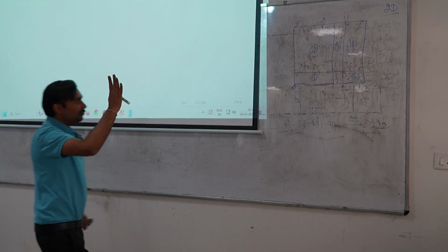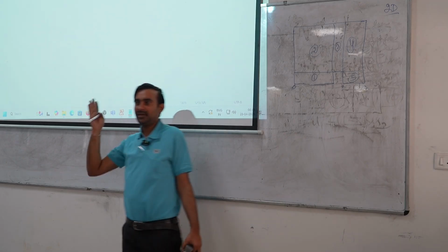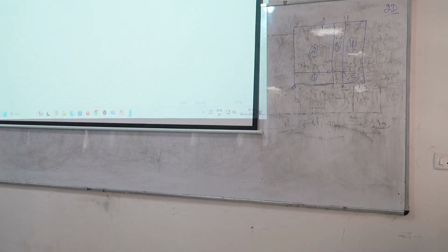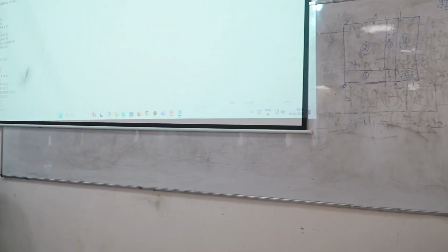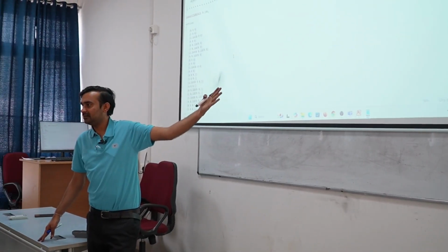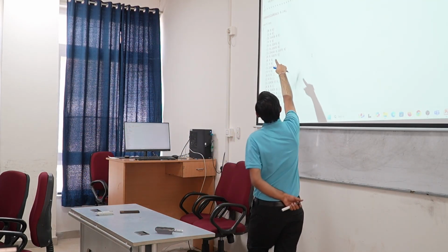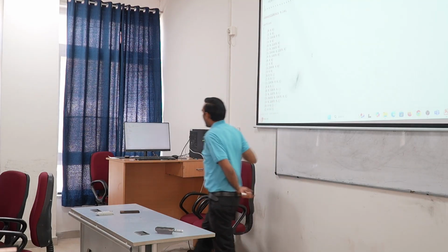But as I told you, we need to define a 3D volume. So in order to define a 3D volume, there should be a backward face of this entire portion. The backward face will have 12 more points. So in total, how many vertices do I need to define? 24 vertices. If you see in this vertices column, how many entries are there? You count, all these are nothing but 24 entries.